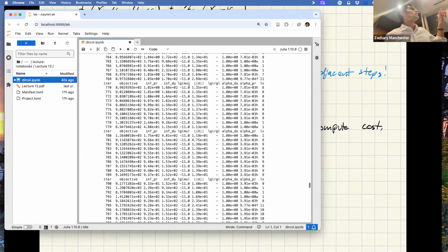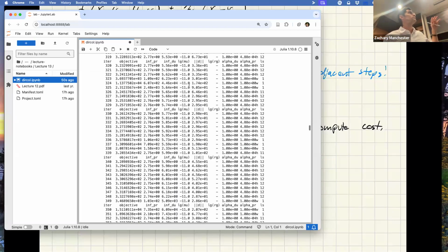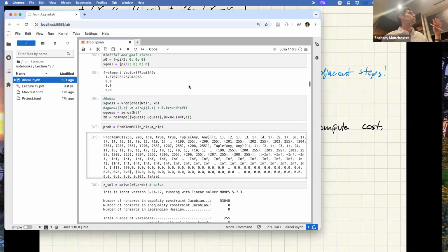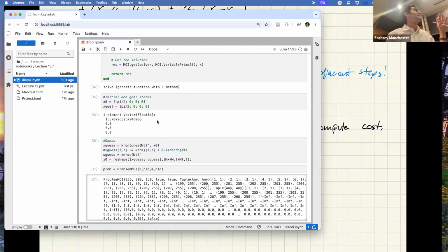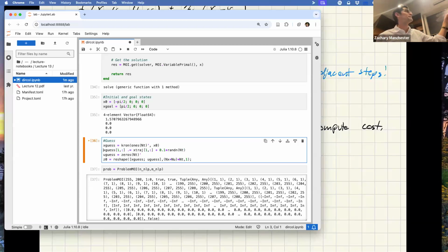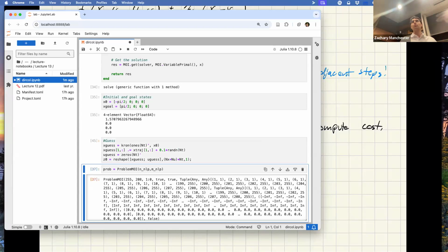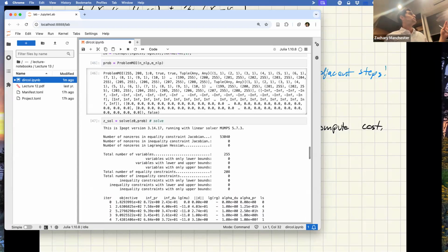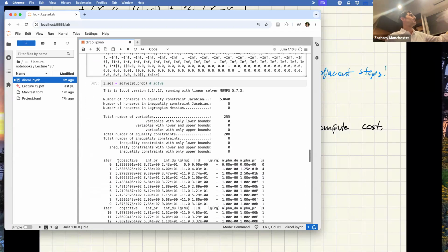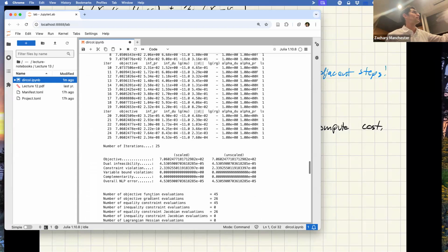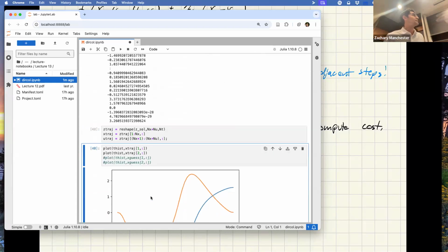So a cool thing about that is, let's say you have some intuition for the problem, or you have some sample-based planner that can give you a guess solution. Anything you know, you can put in here for a guess. It doesn't have to obey physics. So I'm going to do that right now. I'm going to take the solution we just got and put just theta 1, just one of the angles, in there with noise on it, nothing else. So it doesn't obey physics. It's not the whole solution. It's only one of the 4 states. But now if I resolve this, it solved almost instantly, right? It took 25 iterations, less than a second, and it got me the answer.